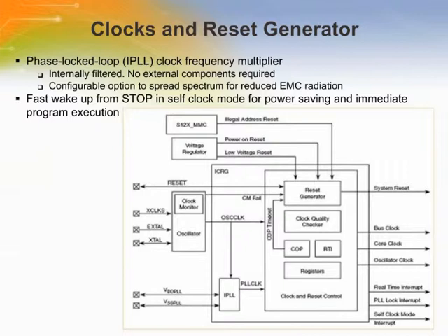Reset is an active low bidirectional reset pin. As an input, it initializes the microcontroller asynchronously to a known startup state. As an open drain output, it indicates that the system reset, which is internal to the microcontroller, has been triggered.